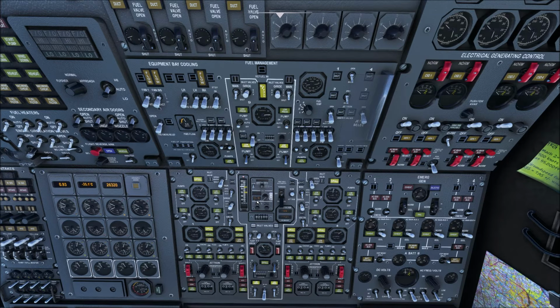And you should immediately start to see fuel transfer. There it goes, creeping up. Fuel will empty from this tank, there it goes, and increase in this tank, thus shifting the centre of gravity balance, and you can just leave that running and it will do it all for you.